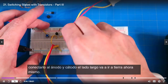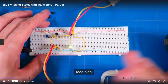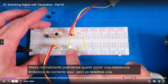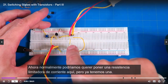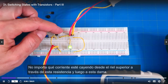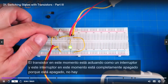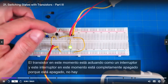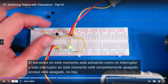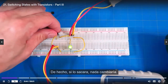Now, first you notice it's on, and we're going to talk about that in a second. Normally we might want to put a current limiting resistor here, but we've already got one. No matter what, current is flowing from the top rail through this resistor and then to this LED. The transistor right now is acting like a switch, and it's completely off. Because it's off, there's no current flowing through the transistor. In fact, if I were to pull it out, nothing would change.